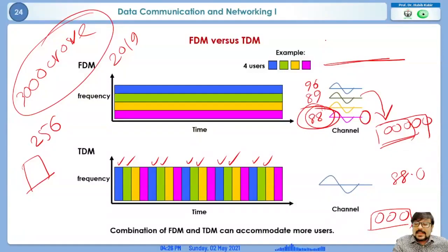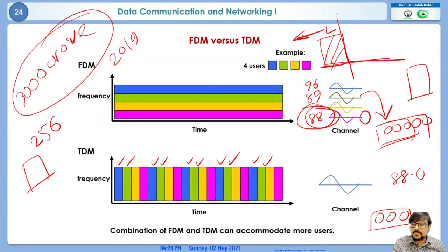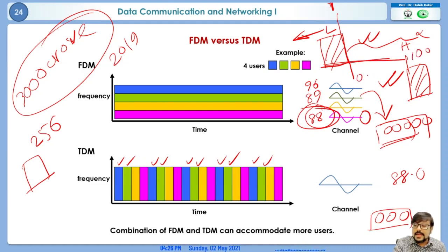So whatever Sakib also said, we have two kinds of filters. I use the tuning filters. So we have a low frequency filter. Low frequency filter means there will be some boundary, and it will allow any signal lower than this. Another filter is known as the high filter. It will attenuate anything higher than this. So we will allow anything over here, and this one will allow anything over here, and will attenuate all the things lower. So if you use like 1, that means I'll allow anything above 1, anything till infinity above 1. And here if I say 100, from 0 to 100 anything I'll allow, and from 100 to infinity I'll not allow. So this is low pass and this is high pass.